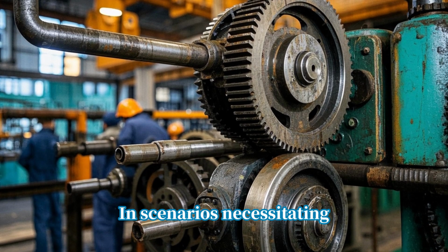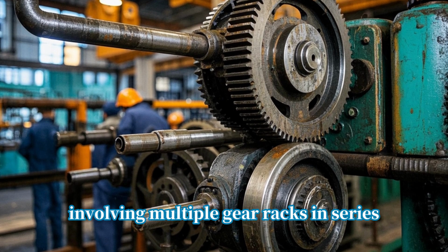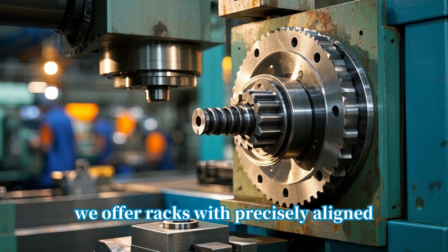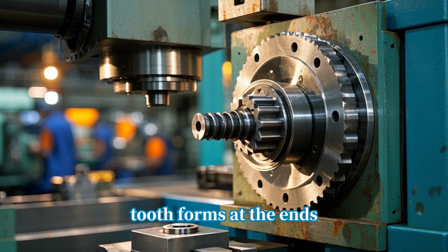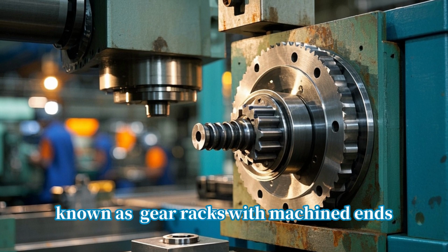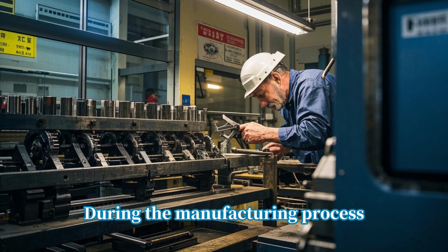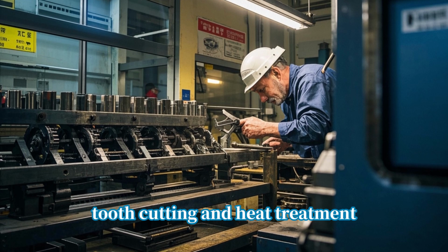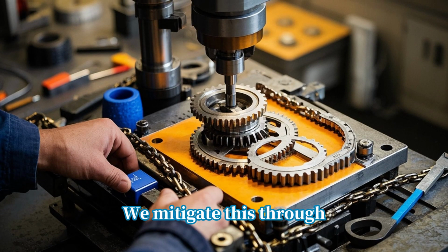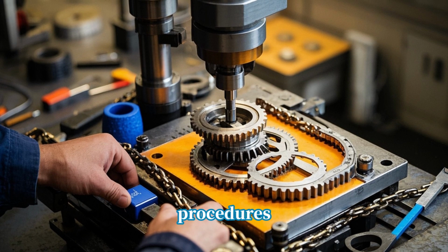In scenarios necessitating a prolonged rack length involving multiple gear racks in series, we offer racks with precisely aligned tooth forms at the ends, known as gear racks with machined ends. During the manufacturing process, tooth cutting and heat treatment may result in dimensional variations. We mitigate this through specialized pressing and corrective procedures.